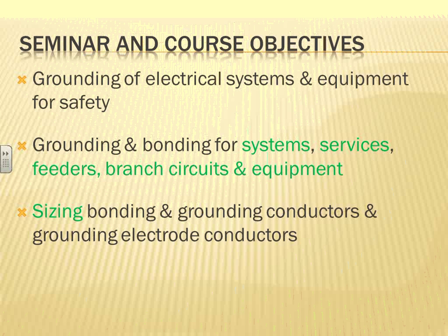Typically in manufacturing, if you need an ungrounded system, you start with a grounded system and then create an ungrounded system internally. If you have a factory with an assembly line, you have your 480/277 that you distribute to get your lighting system. The key point is that with 480/277, you burn all your lights at 277, which is a very efficient high voltage to burn equipment at.